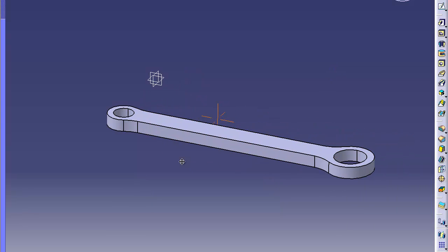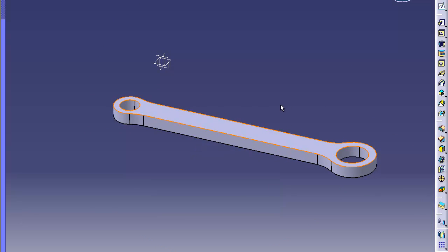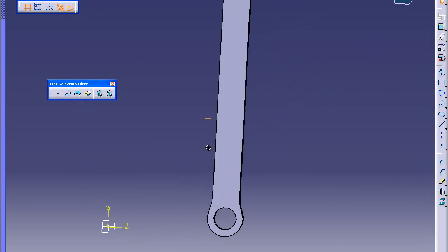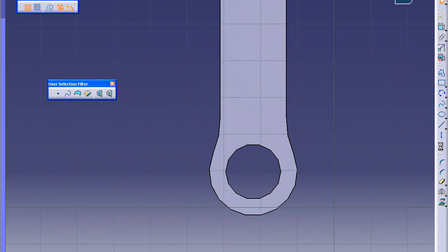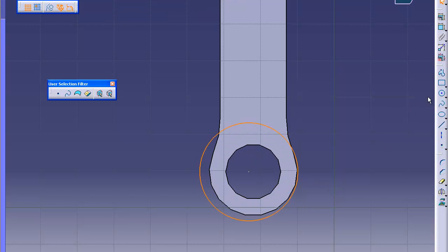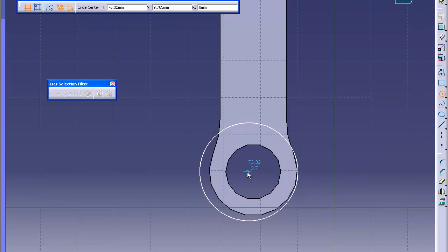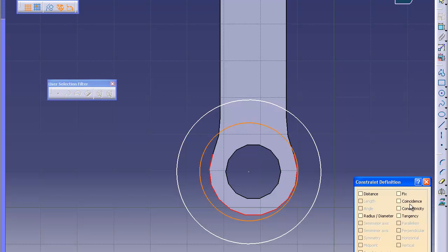Alright, the remainder of the sketch is pretty easy. We just have to enter this surface, go to Sketcher, and create two concentric circles on the thin end. The radius does not matter at this point. So there's one. And so long as we make these circles concentric and coincident with the edges of our solid, we will get the shape that we want.